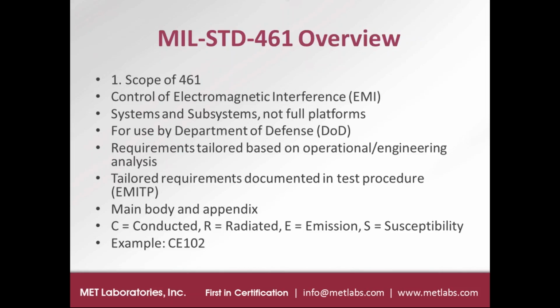So the scope of MIL Standard 461 is for the control of electromagnetic interference, and as I mentioned, it's for systems and subsystems, not full platforms. And I also like to reiterate, not for discrete components. And it's for use by the U.S. Department of Defense. The requirements are laid down specifically, however, the standard allows for tailoring of those requirements.